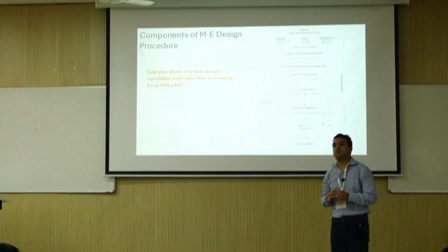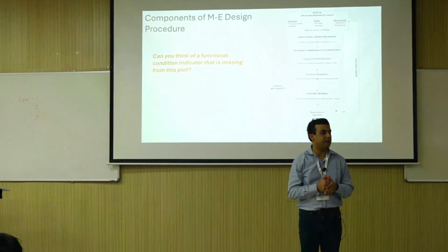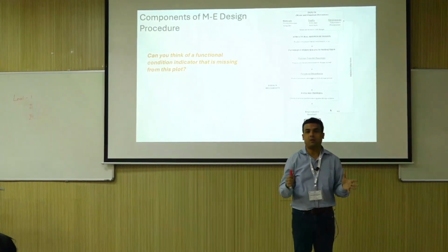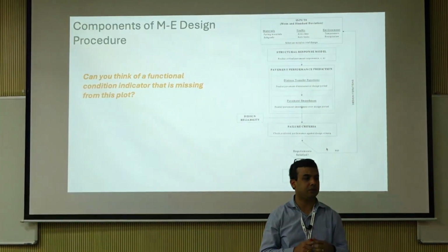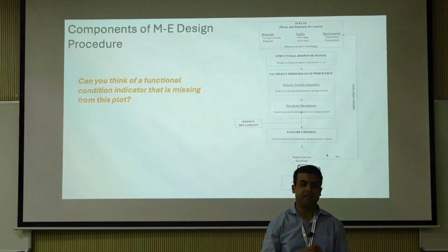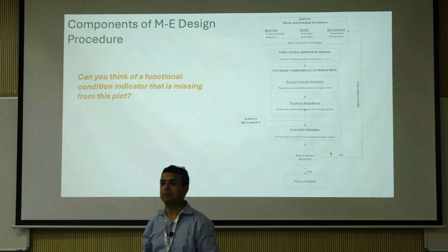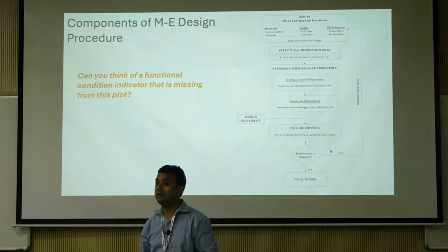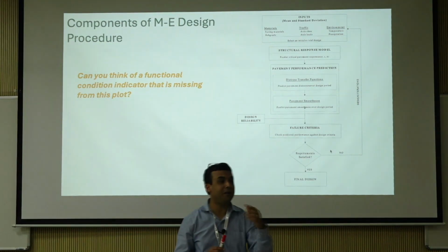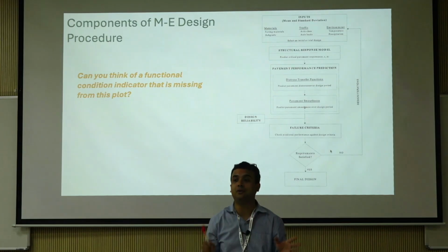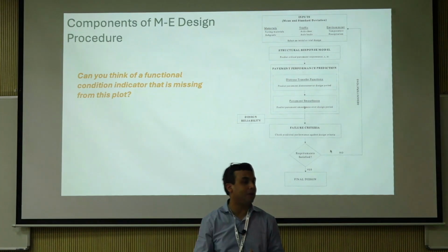How do you test the construction of a subgrade on a roadway in the field? Who has worked in the field or any internship? How do you test it? Density. Very good answer. Anything else you do? Do you do CBR in the field? So don't say research answers. Density is the only one I know of right now. You know. DCP, do it in a